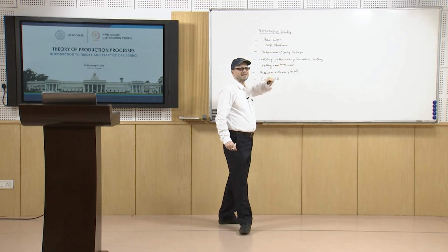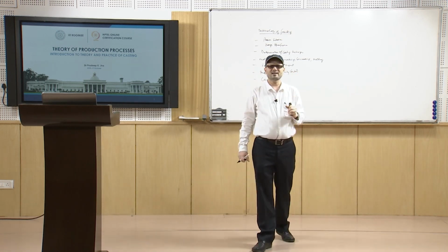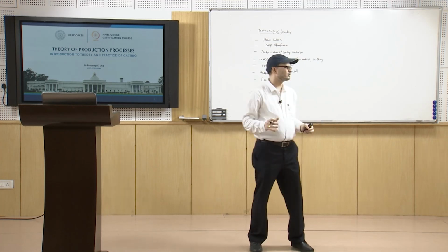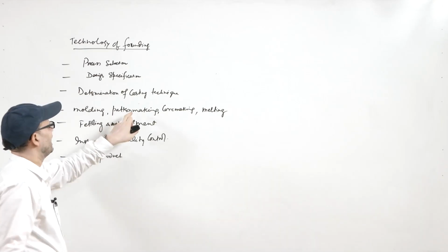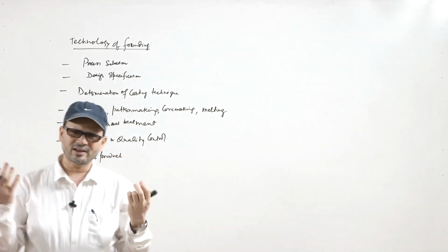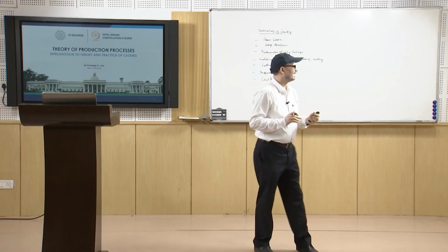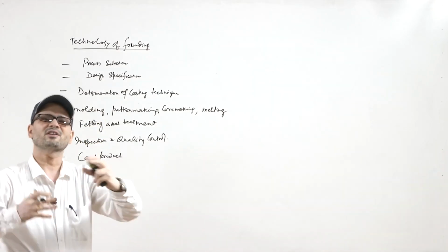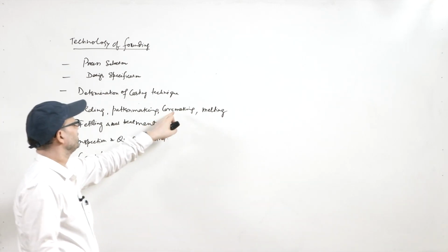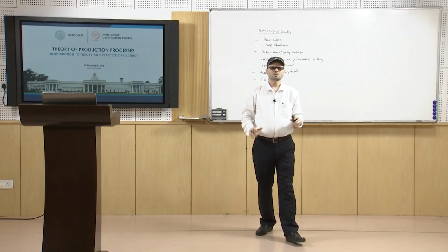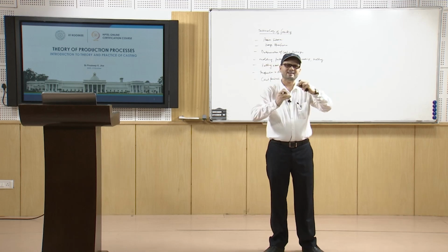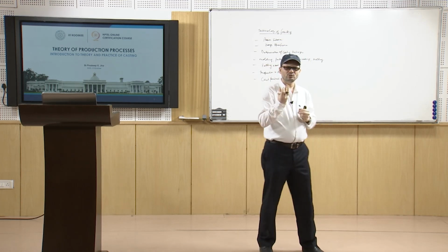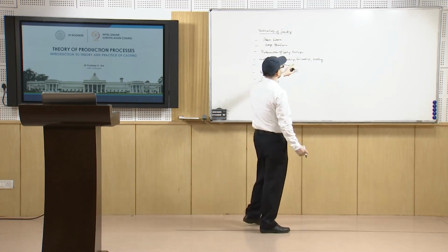So, there will be a section known as pattern making. This pattern may be made of wood or metal or so. In pattern making you will have designers and they will make the patterns giving due allowances, and then that pattern is to be brought to the molding section to make the mold. You will have a separate core making section, so that they will make the cores, so that in the casting if you require hollow projections or cavities, you need a core making section.